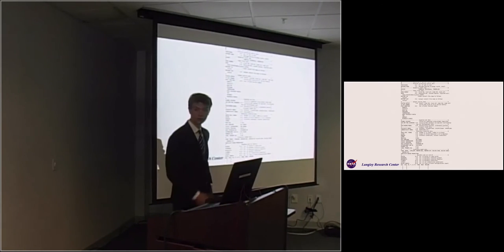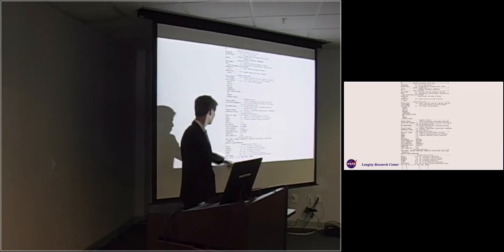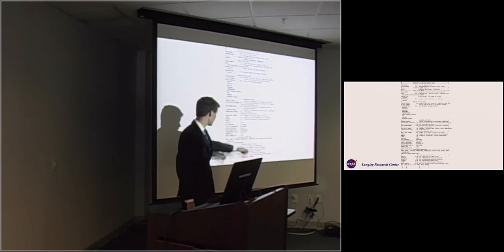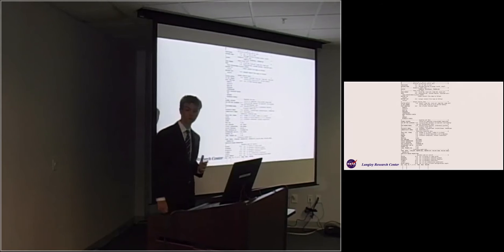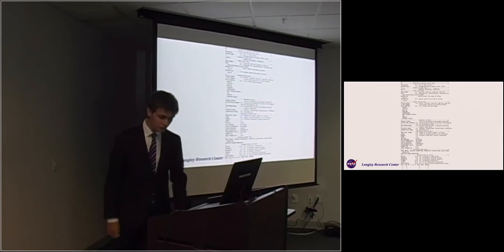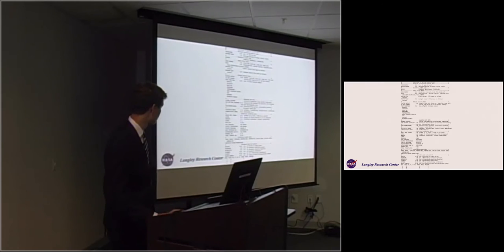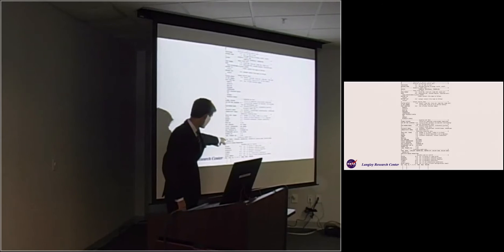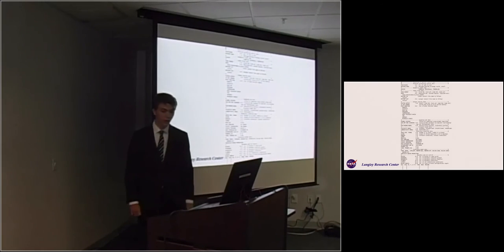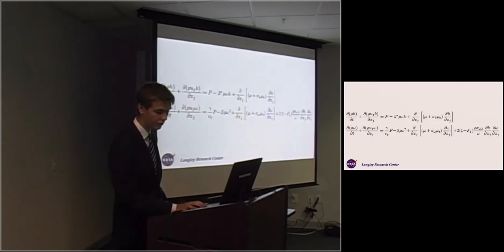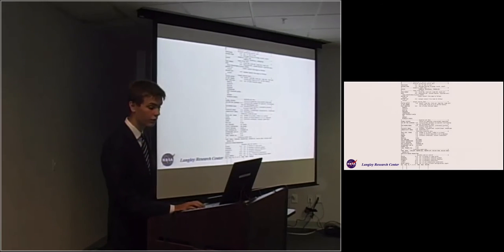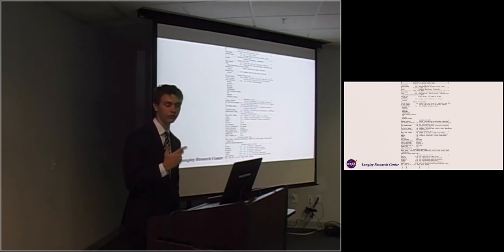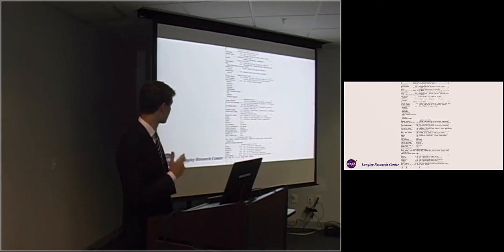So for example, we wanted to say that the inflowing air was traveling at Mach 0.875, that our temperature was 300 degrees Kelvin, things like that. That's under the reference conditions. Also, interestingly, here you can see we specified what model we want to use. In this case, we're using Menter SST, which is the two-equation model. That's the one that Vulcan will use to solve flows.